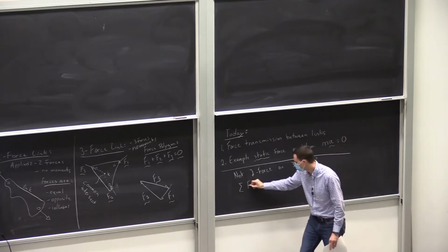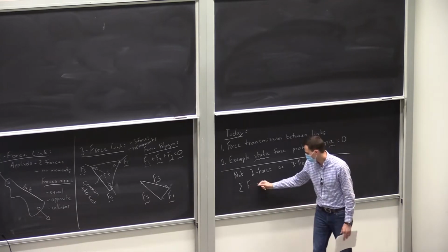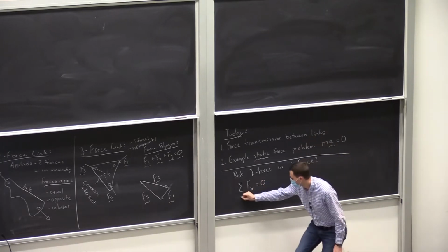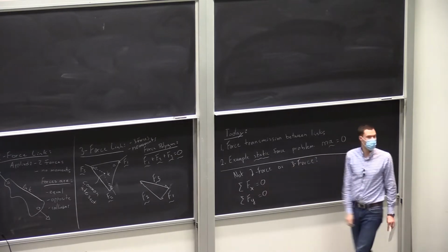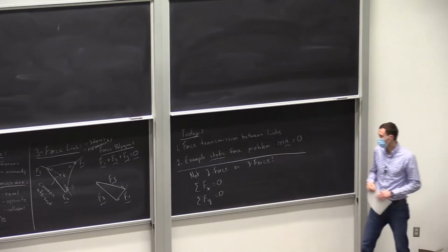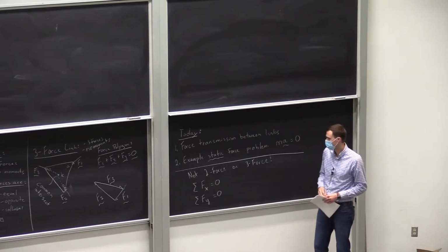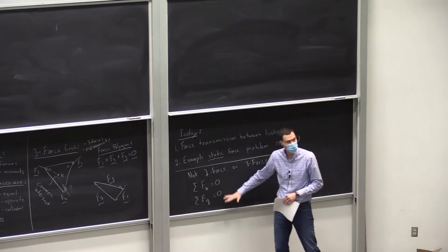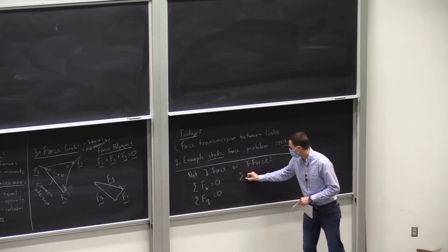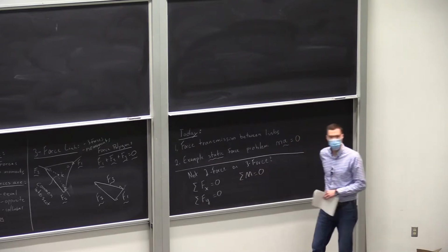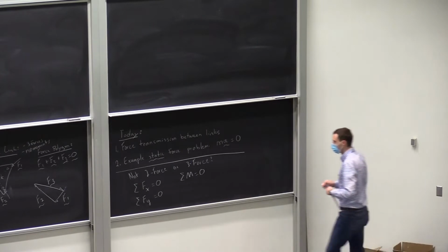So we have sum of forces equals 0, and since force is a vector, you could think about it like x components and y components as one example. These just have to be two perpendicular directions. You could sum up forces in two perpendicular directions. So that's two equations, and sum of moments in the plane equals 0. So you have to write out some equations for those.